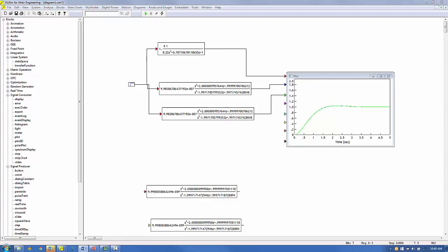Now the discrete fixed point filter response, both transient and steady state, agrees well with both the discrete floating point filter and the continuous filter. As we proceed, we will use a 1 millisecond discrete sample time and a 2.32 format for our discrete fixed point filter.